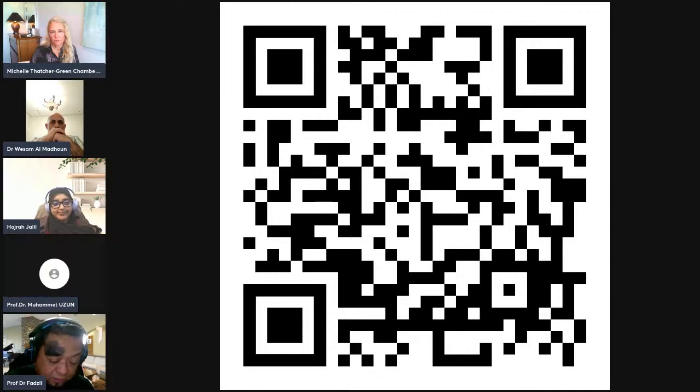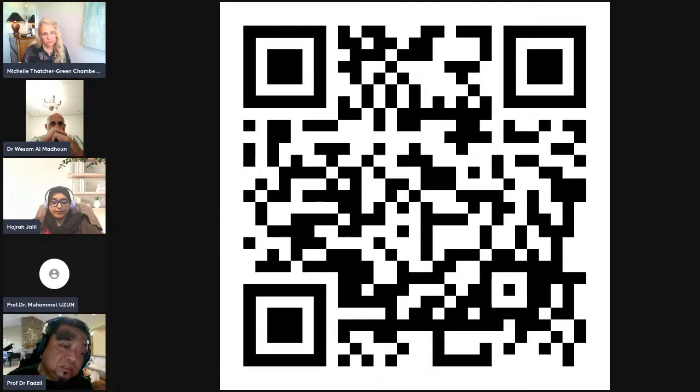And actually this research has been carried out. Last time I had one PhD student doing this research, where he tried his best to come out with the standard specifications for recycled concrete aggregate grade A, grade B, and grade C. We were successful in producing the table, but until today there are no serious takers on the finding. But when talking about designing concrete using recycled concrete aggregate, personally, I would say that maybe we can use it not for structures, but for non-structural materials such as bricks, maybe road curbs, or even drainage.